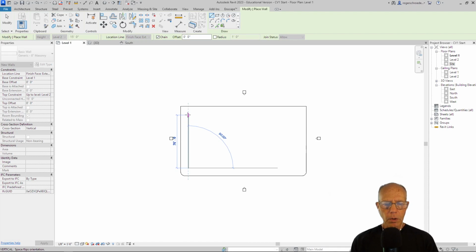I'm going to draw up a wall that I want to be 80 feet long. If yours doesn't come up exactly 80 feet by scrolling out like that, you can just type in 80. And you'll notice I'm ready right away just by moving the mouse. I'm not even holding any buttons down now. I can move over to 30 feet. I'll just type in 30.